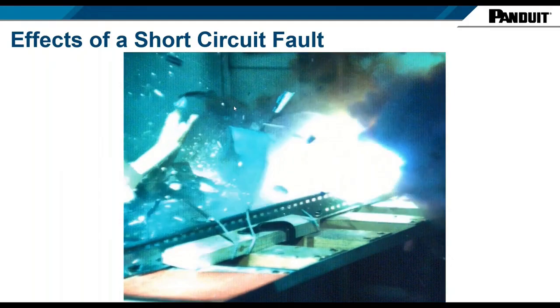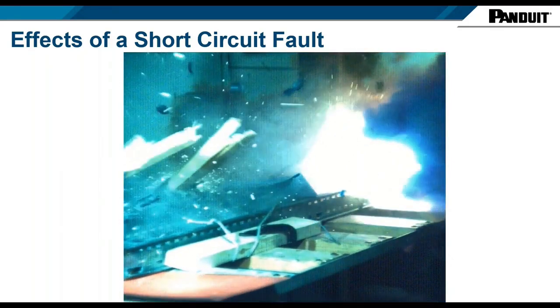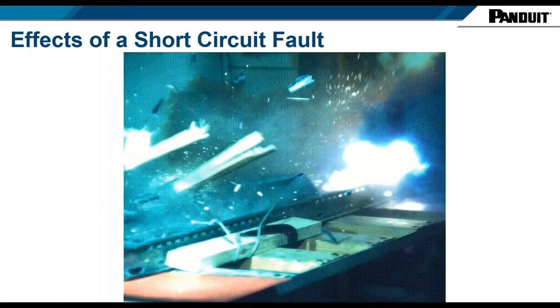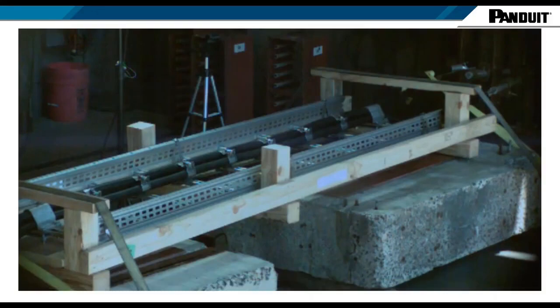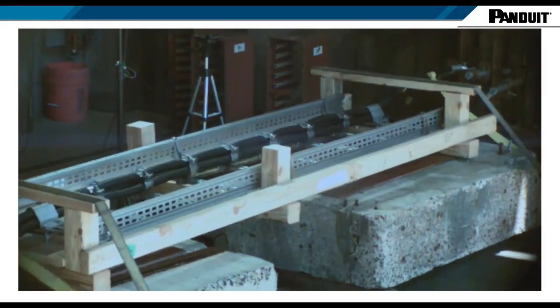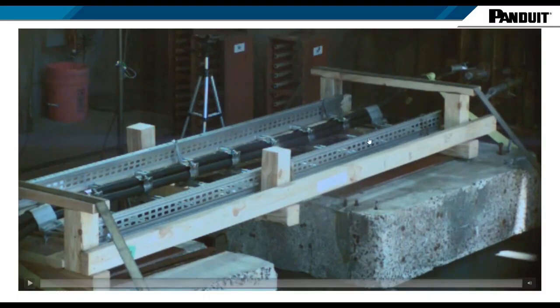So we'll mention our calculator, the way we specify a cleat, later in the presentation. Even when we consider multi-core, we consider a cable cleat. So what should happen? Again, this is a Panduit product. You can see we've got more than 5 tested cleats. You can see the end condition cleats carry out a short circuit. Now there's the peak, but then because the cleats are holding those cables, we get the AC effect. So we get the on-off effect of those magnetic forces.